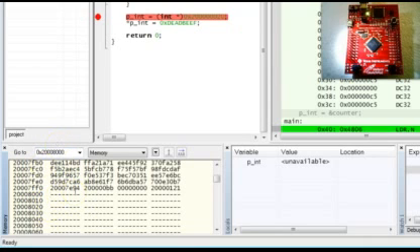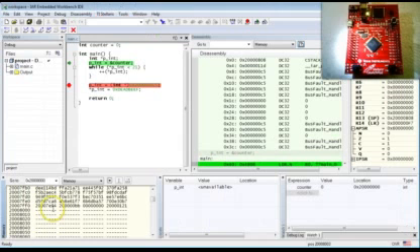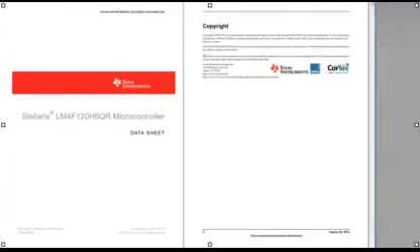However, in order to blink the LED, which is your goal in this lesson, you need to learn more. Ideally, you need to know the map of all the various continents and islands, such as the RAM island, in the address space. The document that describes the memory map of your microcontroller and much more in excruciating detail is called the datasheet. I highly recommend that you download the datasheet for the specific LM4F microcontroller on your Launchpad board from the link I provide in the class notes.